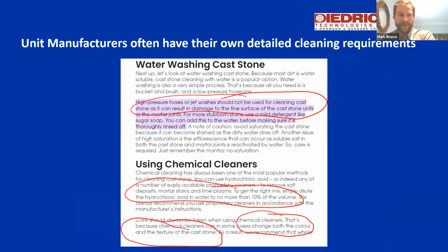So the point is that a lot of times the unit manufacturers, in conjunction with the cleaners, are going to have their own detailed cleaning requirements. If you do get things coming up that aren't aligning when you're talking a cleaning project or a cleaning job, most of the time the manufacturer's literature is going to point you in the right direction to get favorable results. So again, when it comes to mixing and waters, the best rule of thumb is to follow those manufacturer details and data sheets as closely as you can, and you're going to find that you get a lot better results most of the time.